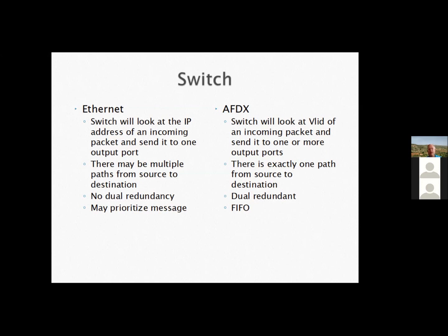So Ethernet does not have dual redundancy. Typically, your computer has a single Ethernet port that you attach to your wire, which is attached on the other side to your switch or your hub. Whereas AFDX always has two. So that's dual redundant. And in Ethernet, you have this notion of prioritizing messages.